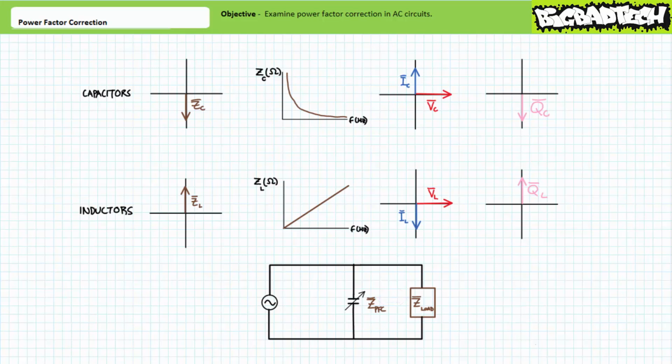It should be noted that most small-scale power factor correction scenarios involve the placement of a variable power factor correcting capacitor in parallel with an electrical load that exhibits inductive characteristics, and not the other way around. The reason behind the regularity of this arrangement is that ordinarily the electrical load in question being power factor corrected is in fact a motor, which ordinarily exhibits inductive behavior.